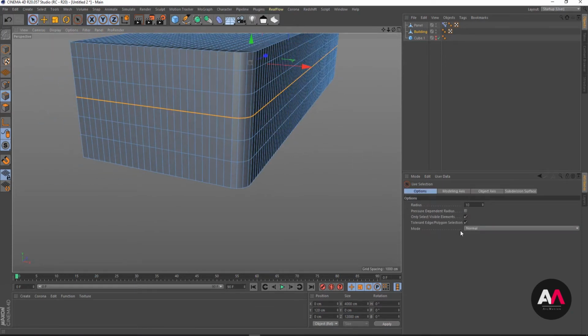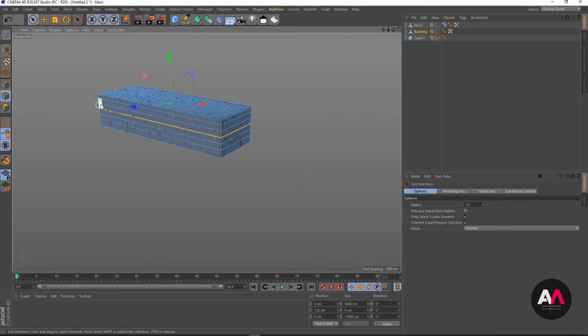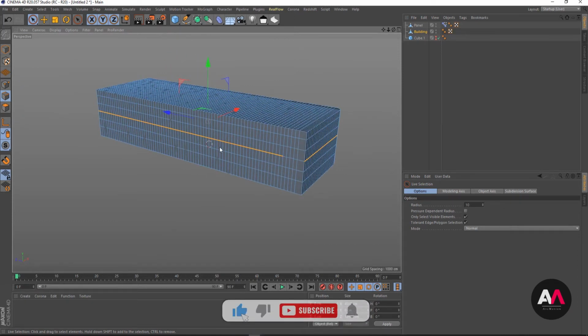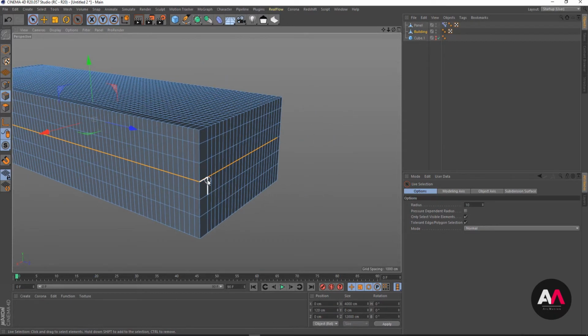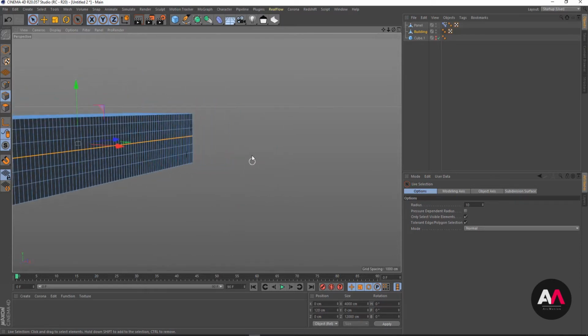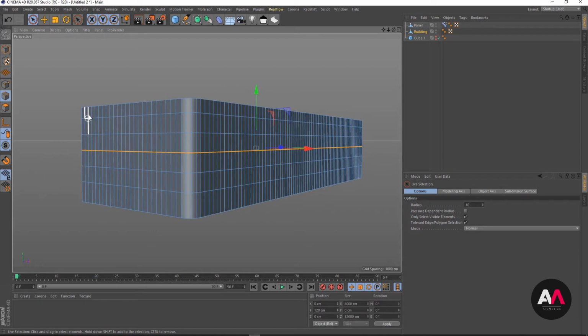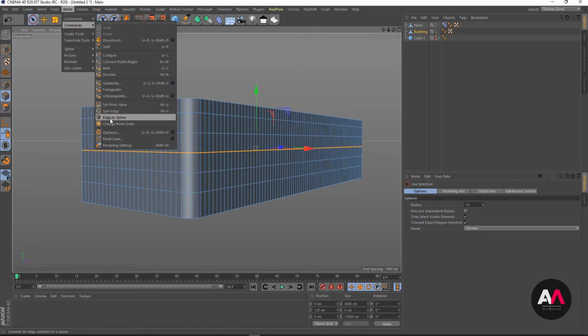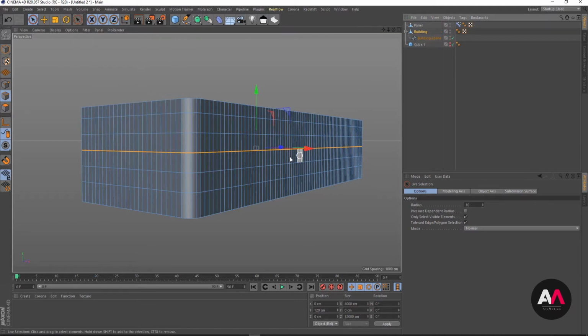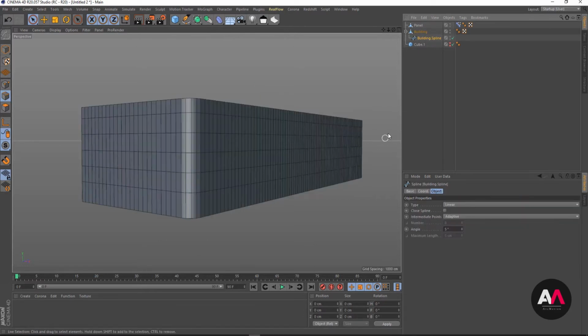and I'm going to deselect the lines in the back side of the building, because we are not going to see it and we are not going to make our model heavy for something that's not important at all, just because we want the panels in the front side, not the back side. Now we go to the Mesh command, and here we have a command named Edge to Spline. It copies the edge that we have and converts it to a spline. So I name it cloner spline.